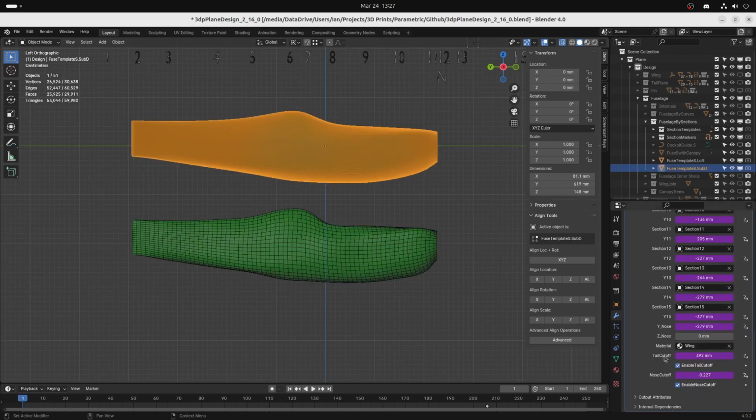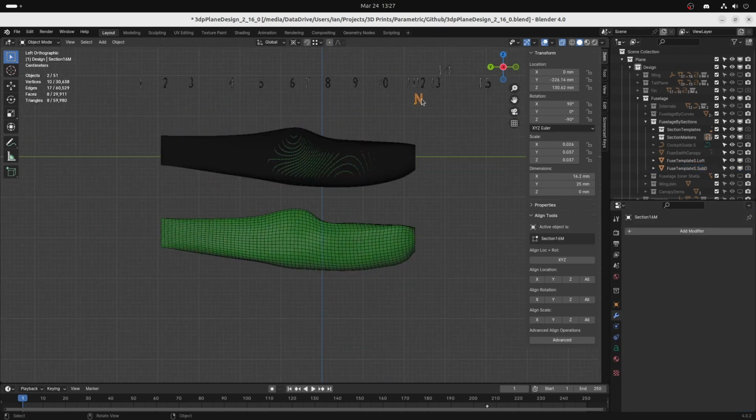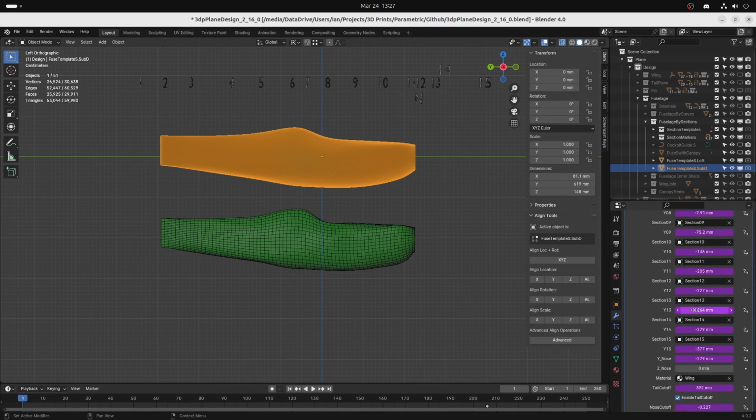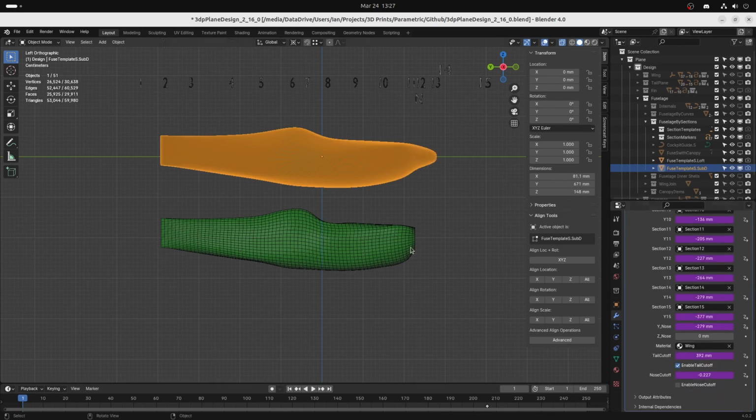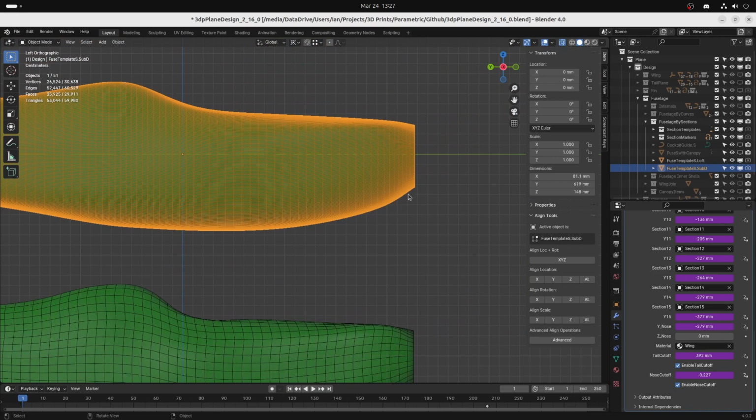For both versions of the fuselage, I've added optional cut-off parameters that make a clean cut at the desired points. I found it was necessary in order to have some control of the shape of the fuselage as it approached the end. For example, you can model the spinner roughly, and then you chop off the fuselage and the shape of the fuse then blends in the correct way to the cut-off point.